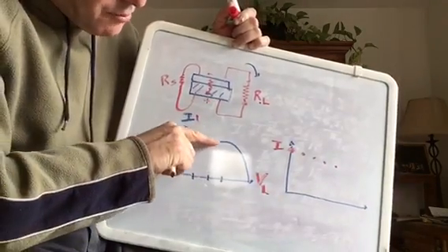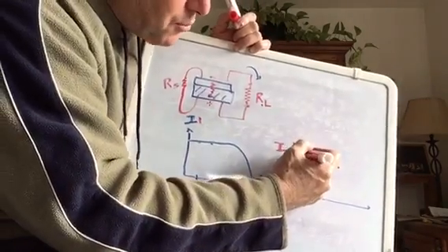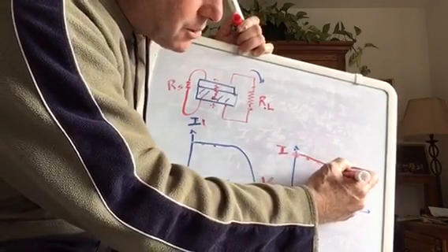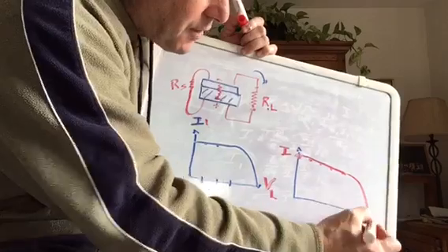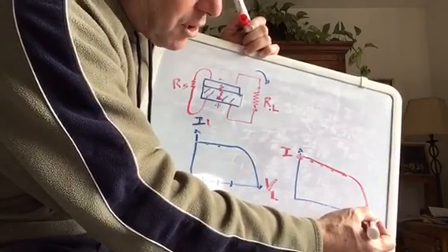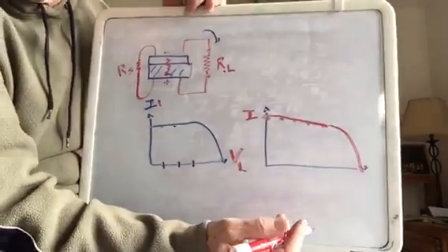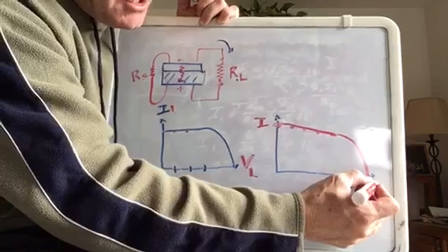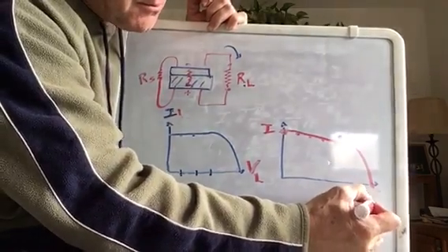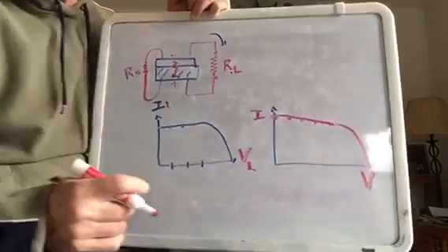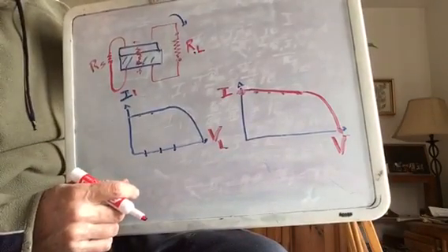So instead of that straight line, the book has a slight downward slope, and then we build it to some sort of resistance and it really falls off. And then when we get a very, very large resistance, which would be equivalent to an open circuit, we end up getting zero current at all. And so over here we have V with the subscript OC, and that represents the open circuit voltage.